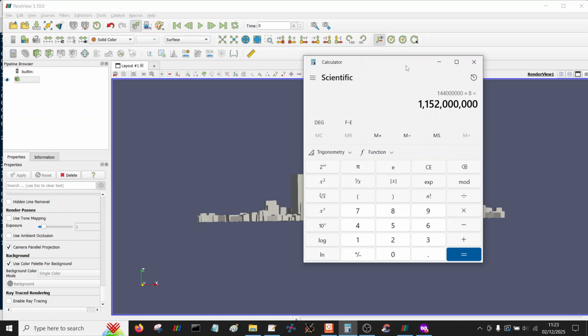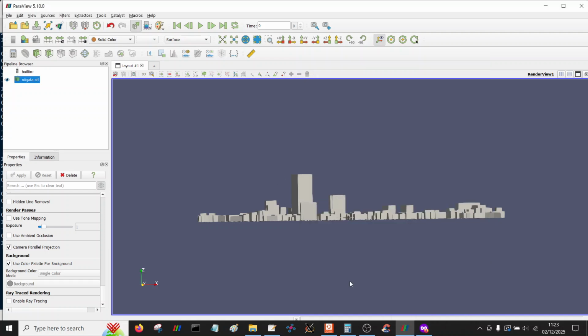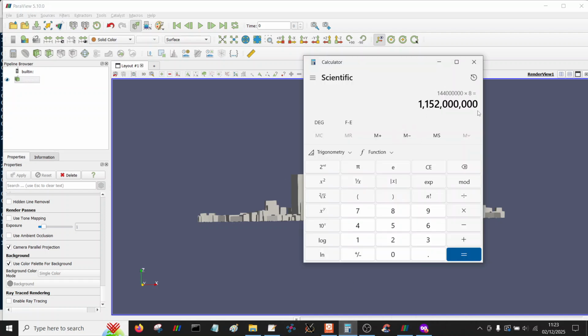So that's why I've come to start using this octree solver, so I can get quicker flow solutions. With the octree solver, you can have quarter meter cells around the geometry, but it's only going to take whatever it was, 50 million cells, and you're only solving on 20 million, so it's a lot more manageable. It's a steady state flow solution, so you're looking for a converged flow solution instead, so it's a lot quicker.